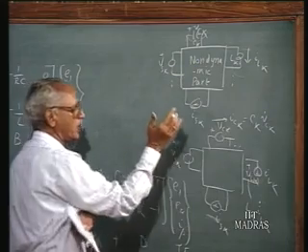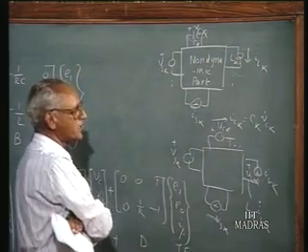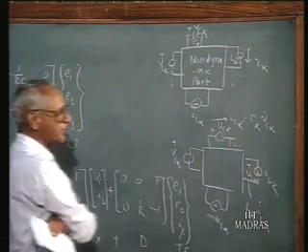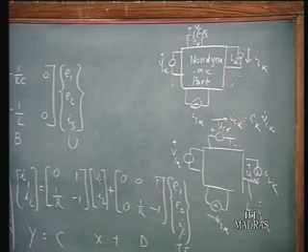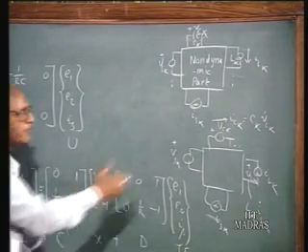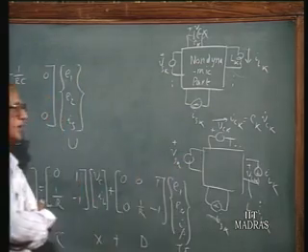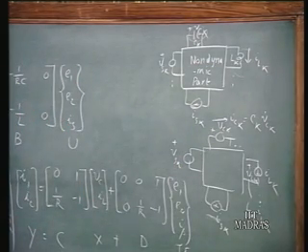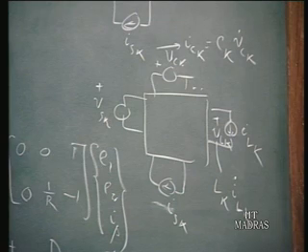The second step is to find the currents in the replacement voltage sources and the voltages across the replacement current sources, and identify them as proportional to the derivatives of the state variables. So you have the derivatives of the state variables expressed as a function of the state variables themselves, the input functions, plus the network parameters, which are R, L and C.